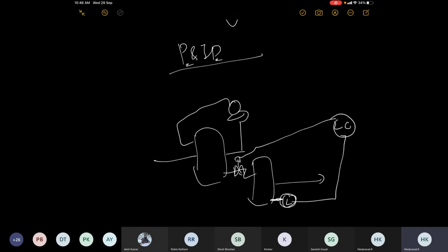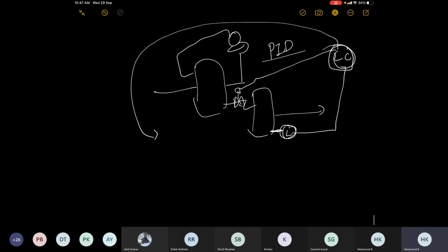Okay, so now if you have your P&ID available, you will know where your controller is sitting. Once you have that decided, you call a control expert or an APC expert, to help you design how you want to control it. The P&ID also will not give you any logic. You say that a level control is needed to control the level from reactor 1 to reactor 2, whatever way. So this third person, who is a control person, which is APC, people will call an APC expert, he would give you all the detailed control logic.